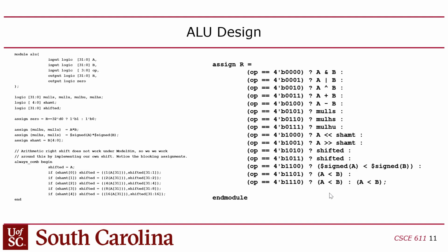So I don't know if any of you can figure this out, like why we couldn't just use the Verilog operation. I'd love to know. Also, the signed multiply was a little weird too, the way we did that. We said assign, we had to type, so logic apparently, I didn't know this till we did this, but in Verilog, logic is treated as unsigned.